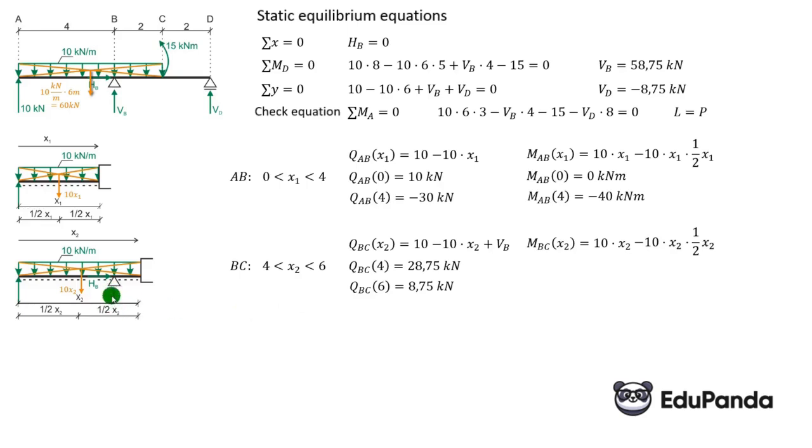So now on what arm does it rotate? It definitely rotates clockwise. Even looking here at the drawing, support VB is 4 meters away from the beginning of the beam, as marked here. Since the whole interval is x2, variable from 4 to 6, this remaining part, meaning the arm of the reaction force VB, is x2, which is the entire length minus 4 meters. And we write plus because clockwise VB times x2 minus 4 meters.